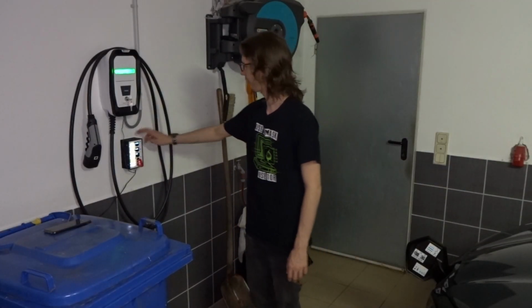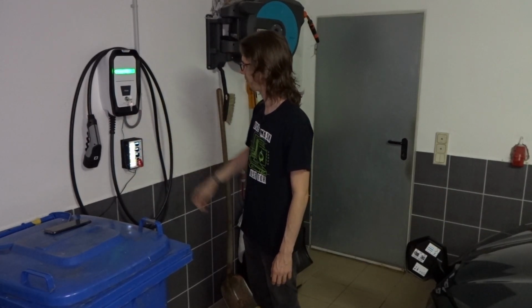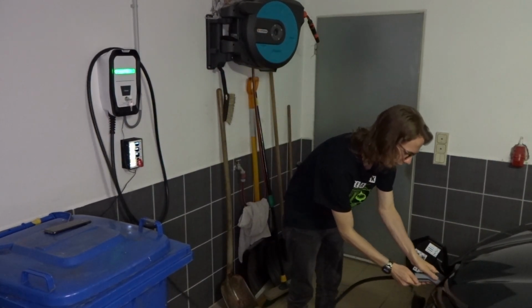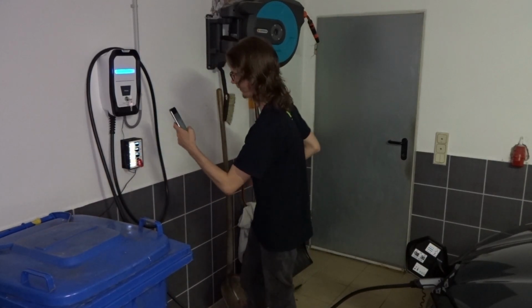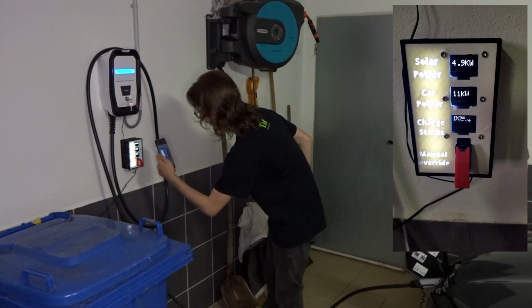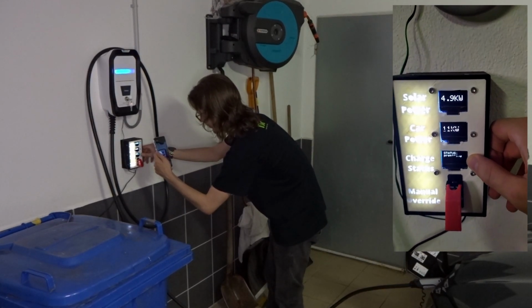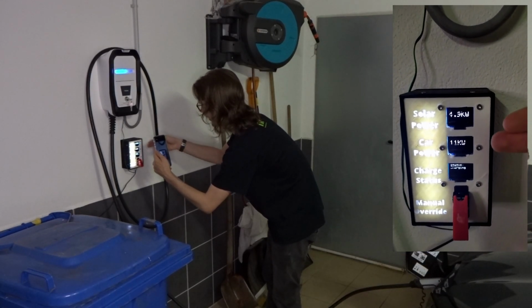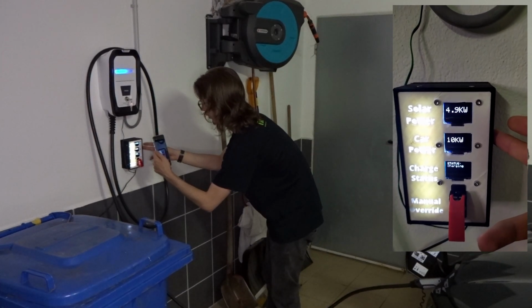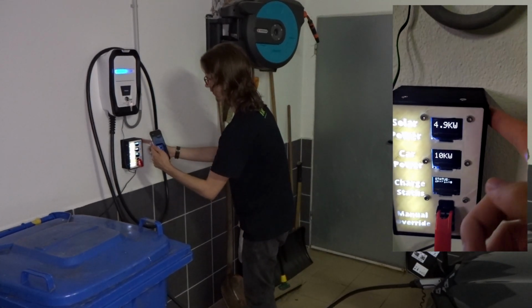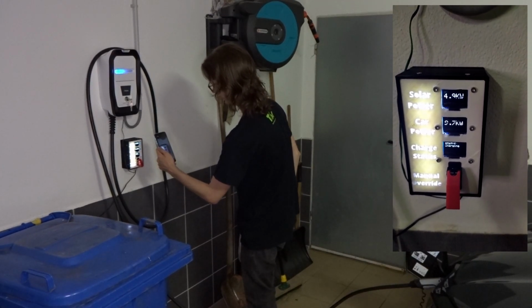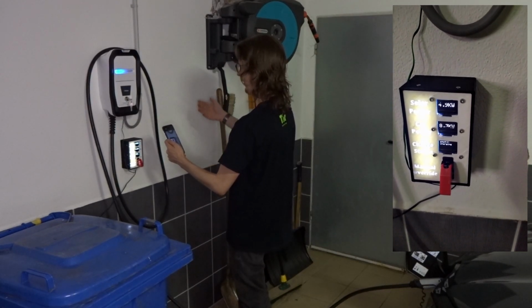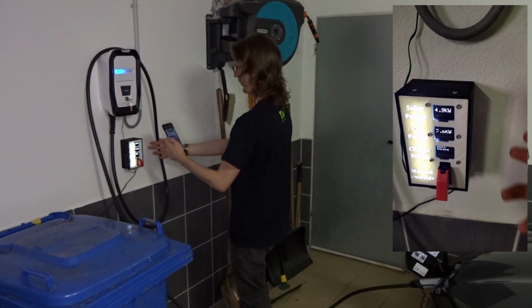So as you can see, the controller box is screwed to the wall and hooked up to the wall box. So now if I take the power cable for my car, plug it in, it detects the car is plugged in, now it's preparing, and it switched over to charging, and now it will slowly decrease the maximum power for the car based on the amount of solar power you're generating. It's basically a feedback loop where it checks how much power is generated and then steps up or down the power limit.